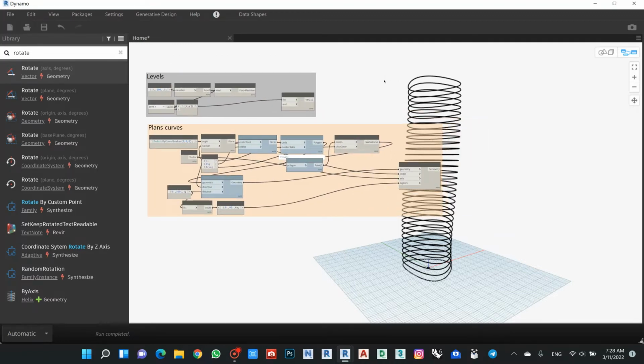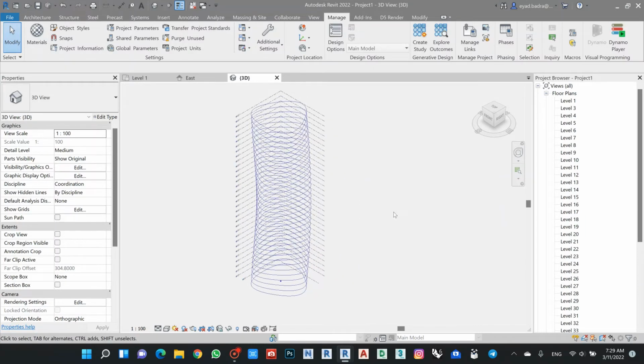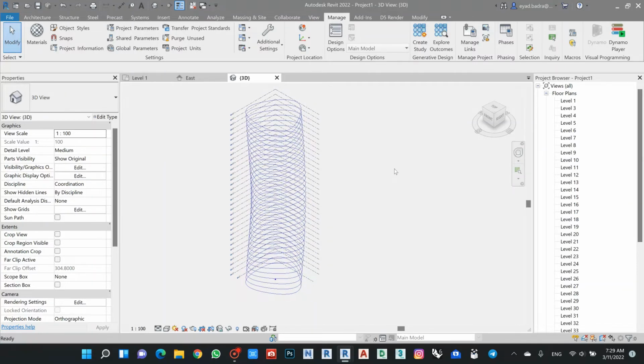So if I go back again here to the pivot, as I can see here, I also see the legend that I did in Dynamo without any actual elements in the Revit that I can use. The only actual ones are the levels that I already created. Let's start to make the floors for these plans and reflect it to my Revit file.